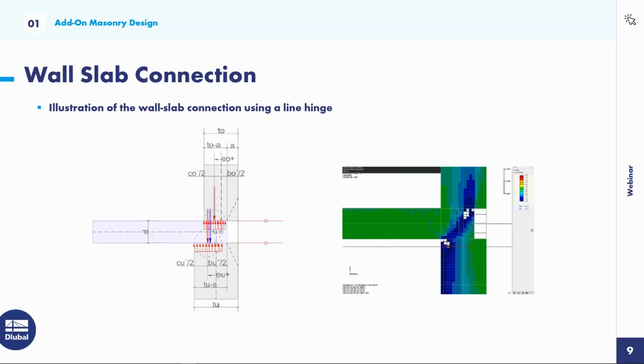Our FE elements are internally divided into 9 layers above the thickness. If the allowable force is exceeded in one layer, then it fails and the wall thickness decreases, and the connection will react with lower stiffness.